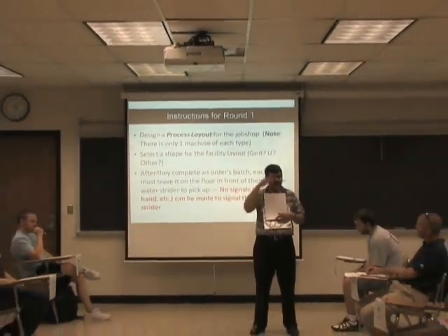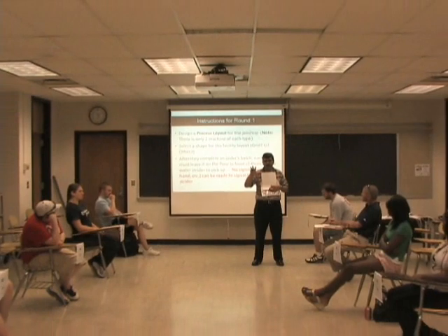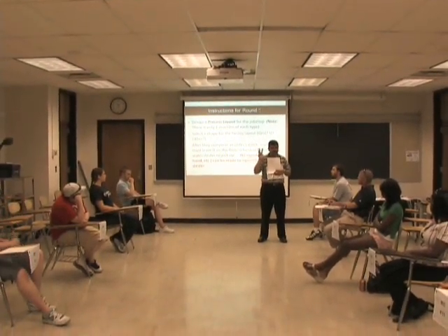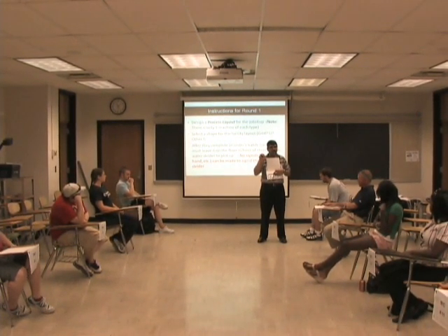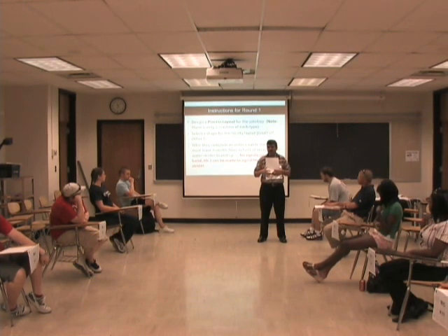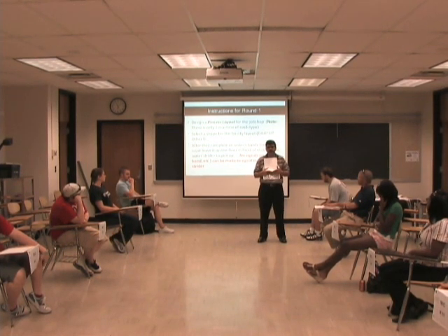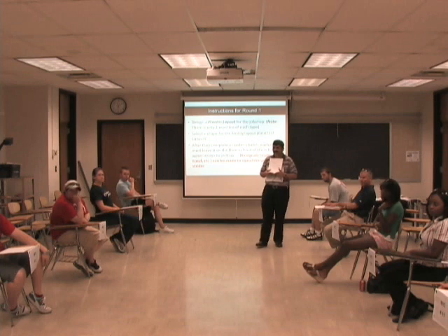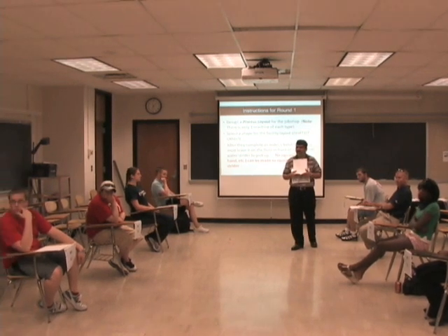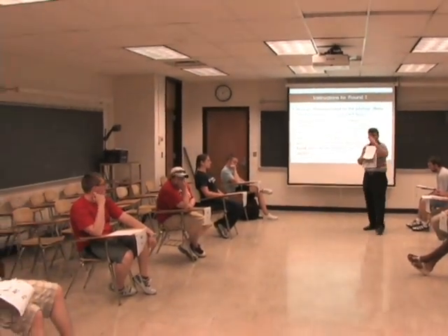Again, I'm trying to sort of review the entire course, so please don't hate me, but I'm hoping to kind of bring together a lot of what I've taught you, methods, solutions, ideas together. So how do we design a process layer? I've got 12 machines. Yes, obviously. Maybe make a from-to chart. Good. Then a flow diagram. Good. And based off the largest flows. Good.